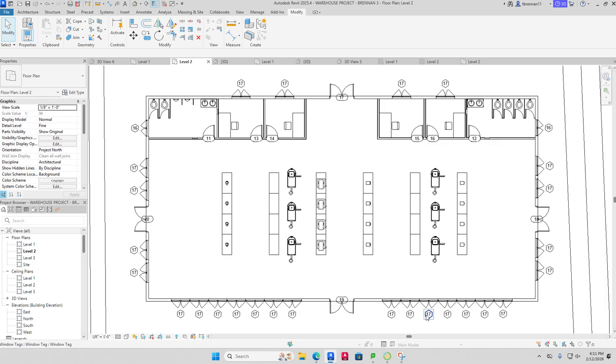It's out the table. Yep. Okay, go back and select one of them. And just grab it. And for this one, you just change the elevation level. Just go ahead and change that to 2.5. That's 30 inches. And apply. There you go. Okay. I think that's it.